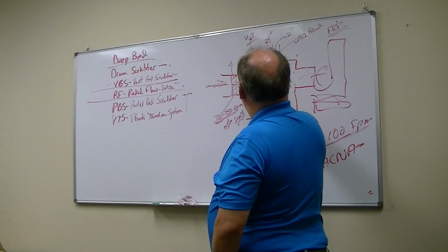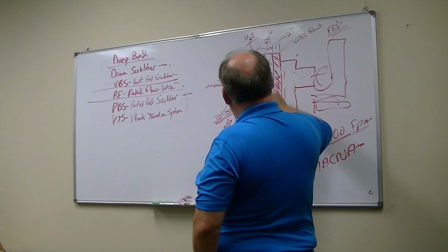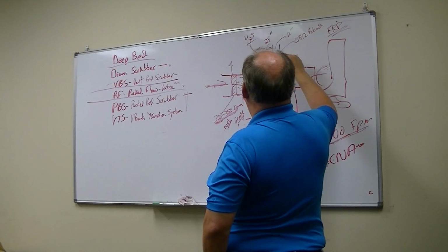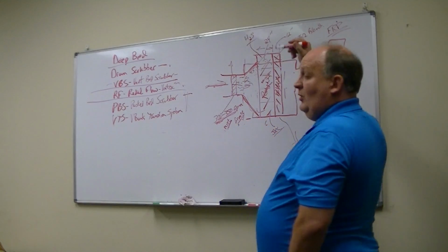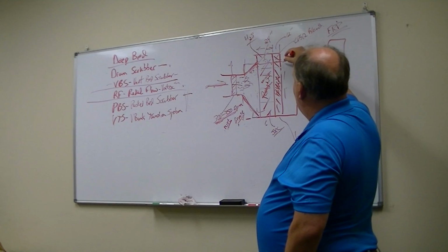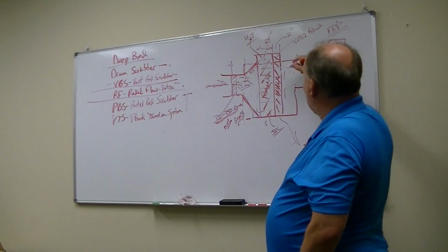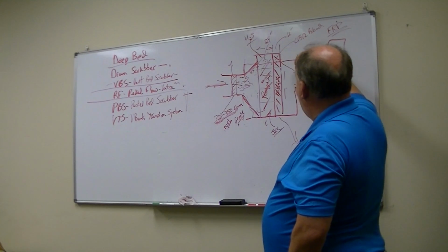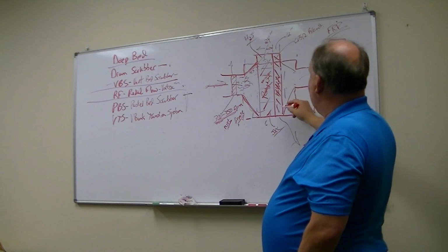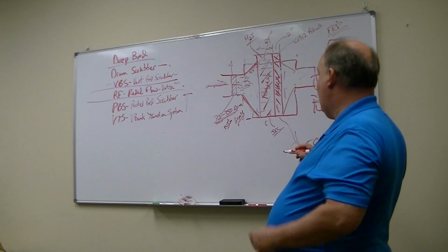So the air is going to come in. It's going to go through this screen. It's going to go through this adsorbent media. It's going to go through this screen. It's going to go through this adsorbent media. And then we have to do the same thing on the reverse side. So it depends. If you've got an external blower, then you need to allow for that same kind of 45 that's coming in so that the air is flowing well in there.